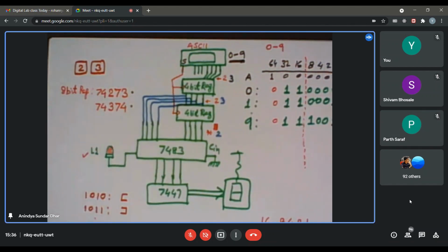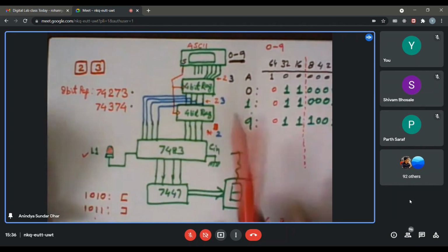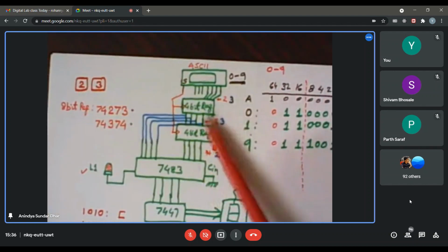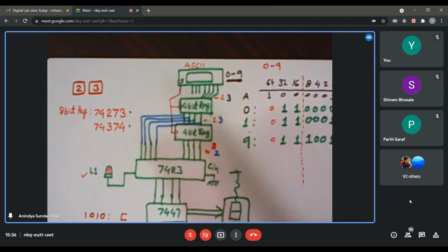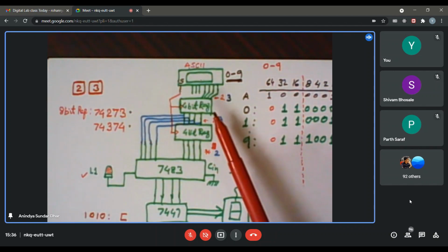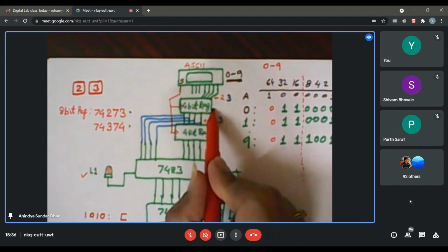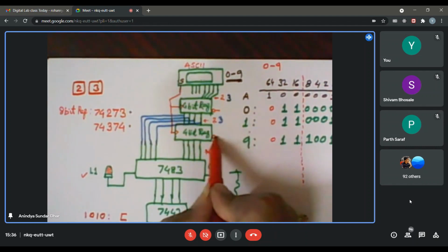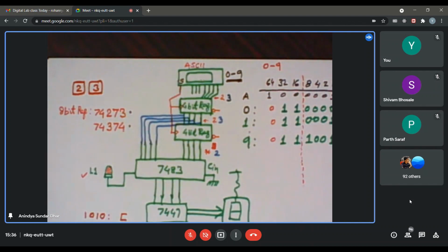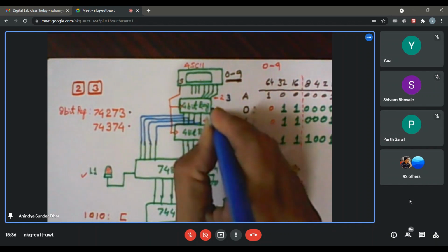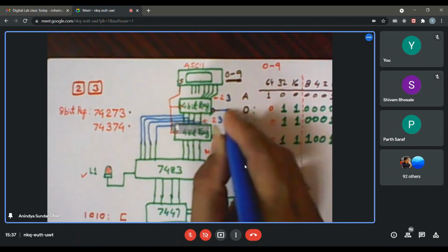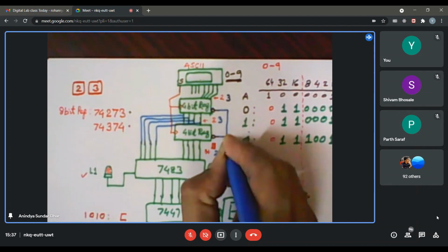No, MR is just for resetting, right? When we would like to reset, I think in this drawing I am not showing that. In the simulator when I opened it, probably you have seen that. The master reset, if I like to show it here, how will it work? If I make it low, then it will reset those registers. I may like to put both the registers to the reset state simultaneously, then I will connect them together. Maybe I use a different color to indicate. Whatever I am drawing, is it visible? Yes. So if you wish, you can keep them separate also.